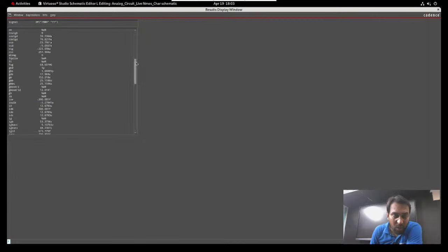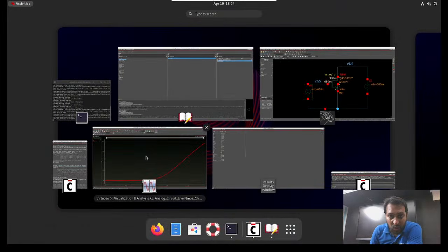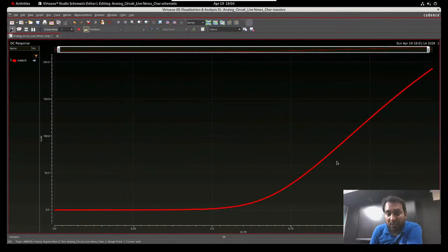But if you want, for every VGS value, the region, the CGD, the CDS, the VTH, in such a way, just like the graph shows ID versus VGS, for every value of VGS what the ID is, but here you are not getting the region or the value of VTH for different values of VGS. If you want it in such a way, you can use some extra part in Cadence. Let me show it here.